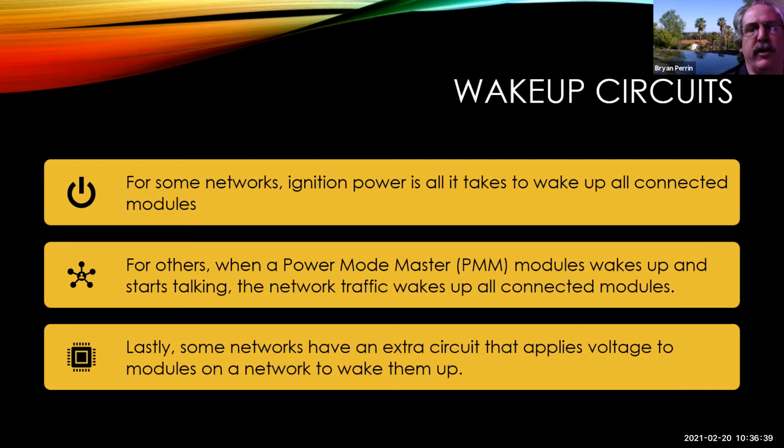We looked at one in the transmission class I did yesterday, and the flow chart's a solenoid code, and nowhere in the flow chart does it have you check the wiring from the computer to the solenoid. It has you pull the solenoid out of the transmission, test it. If it tests good, put a transmission in it. But nowhere in the flow chart does it have you check the wiring between the computer and the transmission, or even for a signal.